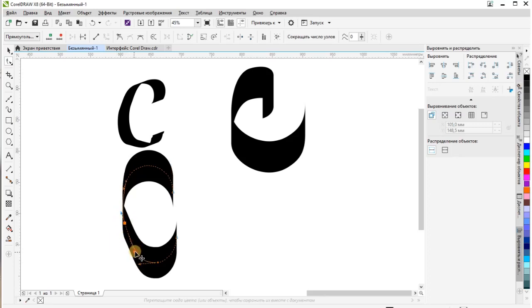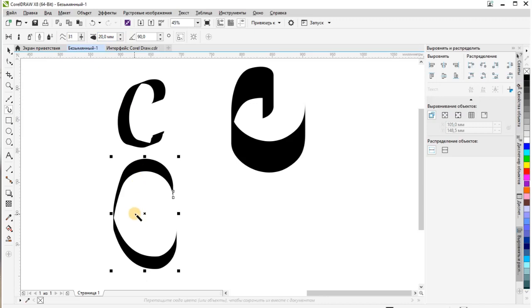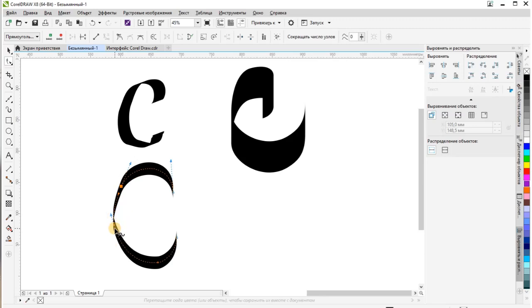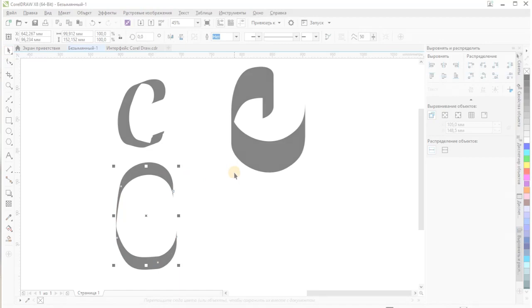This example shows a composite object drawn in calligraphy mode. On the left, it is selected using the Shape tool by clicking on the axis of the object, after which it can be edited. On the right is a view of the object after changing the tilt of the calligraphy pen. Instead of 0, the value was 60.